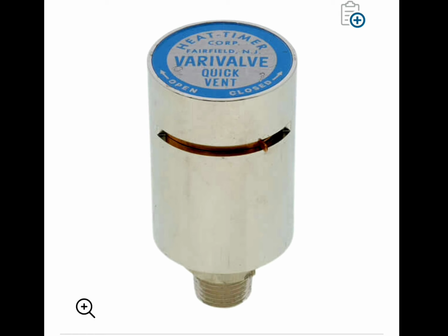Now, this is very problematic to have a vent that has thick brass on a steel convector, a copper convector, aluminum, whatever type of convector that you have. If it's not a cast iron based convector, you should not be using this vent. Like I said, 2 reasons. Number 1, if water ever were to get inside of that radiator, this thing will keep spewing out water.